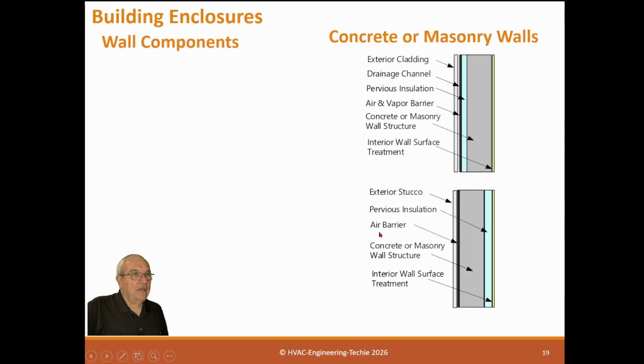So, concrete walls. Okay, concrete walls are the same thing. They have an outer layer. Now, why would we put an outer layer on concrete? Well, concrete is not waterproof. This is one of the problems you have in architectural components. We have a lot of preconceived notions about what is a vapor barrier, what is an air barrier, and how is air stopped and how is water stopped. And boy, a lot of it's not true. Concrete will absorb moisture, so you have to do the same thing.